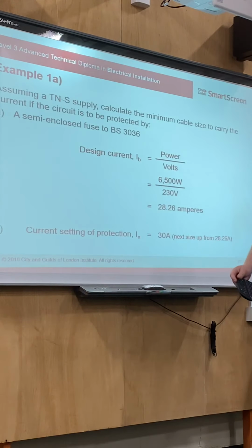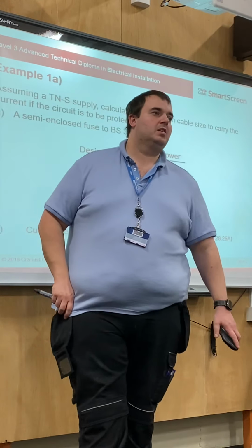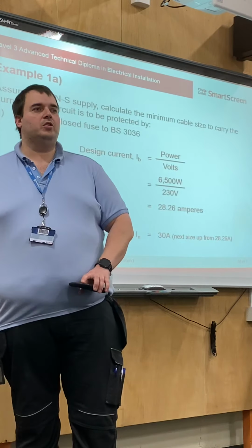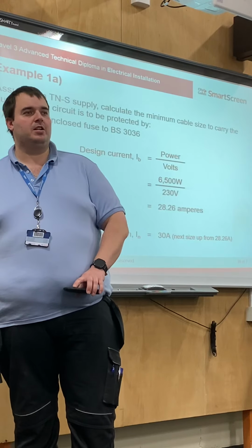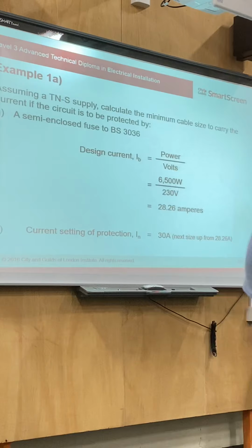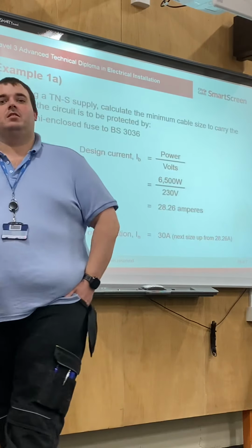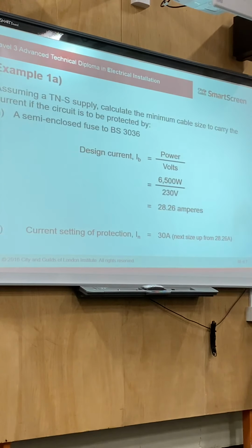Okay. So where am I going to move to next with this? What do you think? So I've got to do something before I can select my cable, haven't I? Can you remember what it was? You've got to work out the volt drop. Before we even get there? Method of installation. What was that? Rating factors. So we've got a formula which is IN.